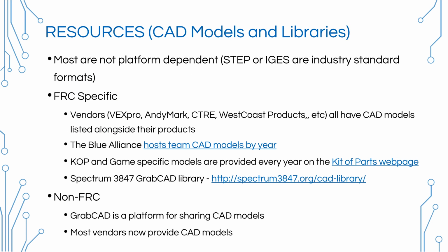So now, one of the things that's important here is CAD creates digital 3D models, and there are actually a few formats which are platform independent and can be imported into any of the CAD programs that we've talked about already. And those are STEP models or IGES models. You're going to lose some of the features. It's basically just going to be the final 3D shape of what you designed.